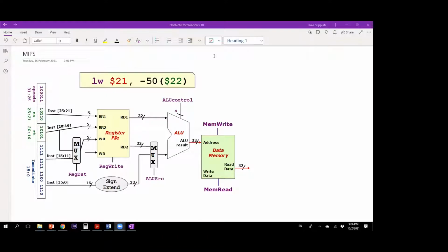Pipelining happens in different stages. That means you look at the 5 stages: fetch, decode, execute, memory, write back. For all these 5 stages, there is a pipeline stage. That means there's a buffer stage to hold information while you move from one stage to the next stage. So that is the idea of improving your system.